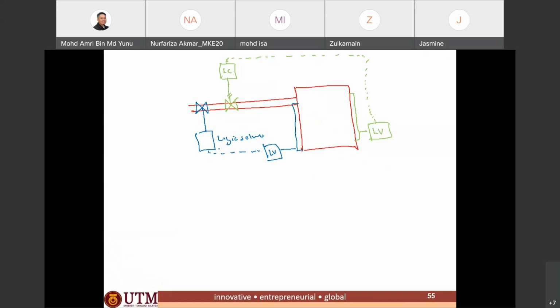Another example is where you have a separate system to control the level of the water in the tank. The safety can be further improved by having another release valve, so that this is fail close, this is fail open. This is to make sure the pressure or the water level is controlled, or to make sure the tank is empty when a failure happens. So that's one example of how a safety instrumented system can be used.